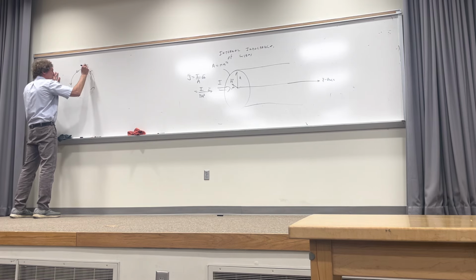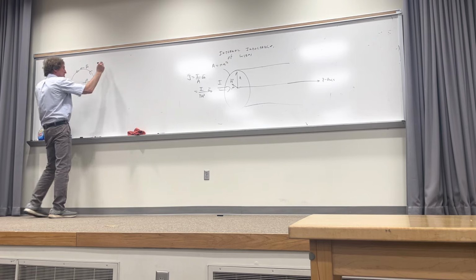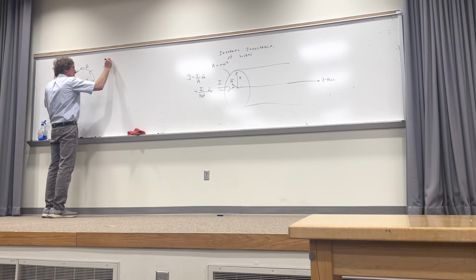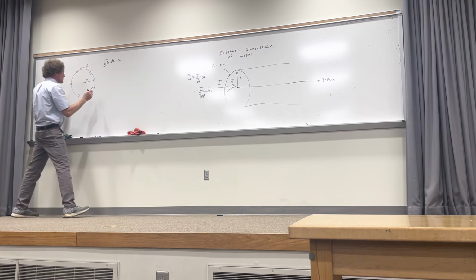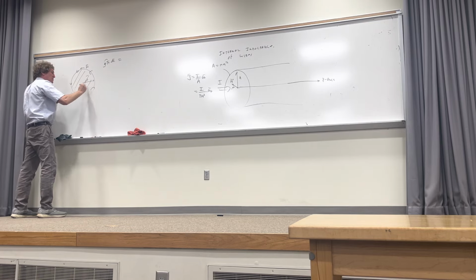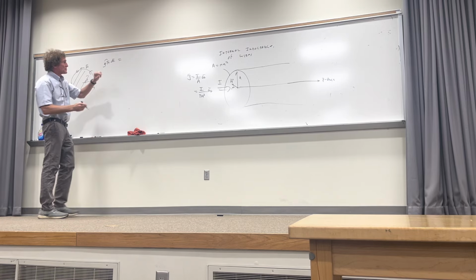So, now for that one, I know if I take the integral of H, right here, this is the direction of the H field, I'm out a distance rho away. If I take the integral of H dot dl around a closed loop, that has to be the amount of current penetrating that loop. Do you all agree with me there, class? That's standard Ampere's law, right?